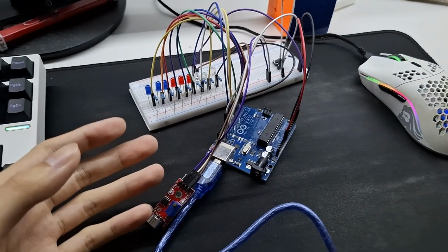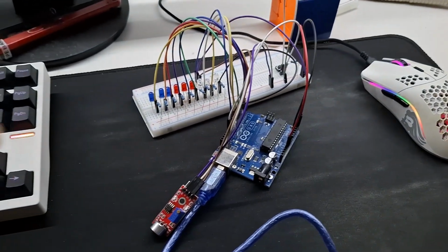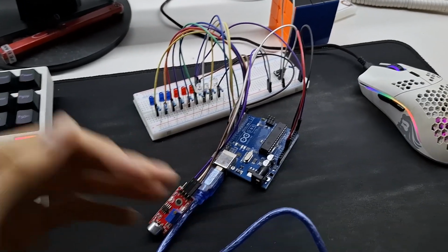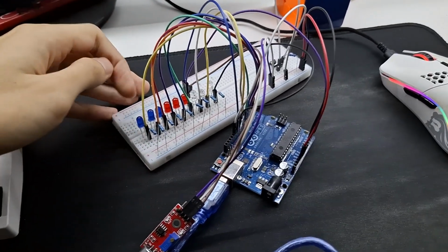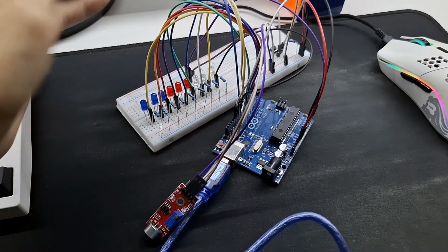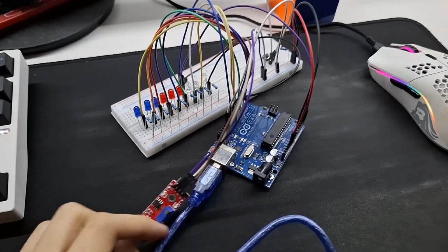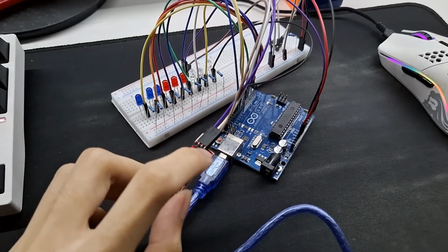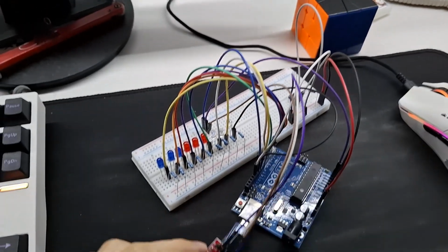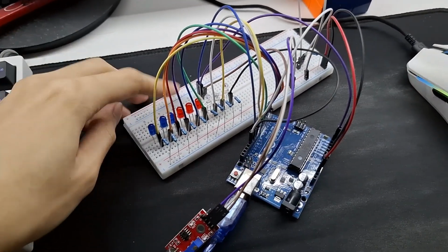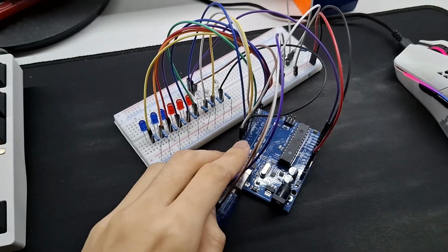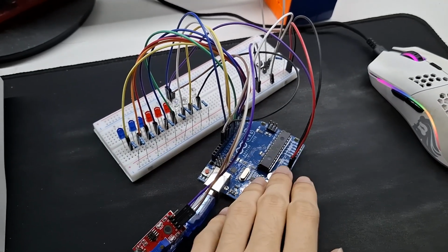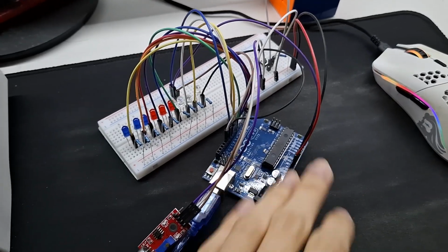to the other mode, which is frequency detection mode. It will detect the sound frequency that hits it and will display it on the same LEDs. All of this is done by splitting the analog output of the sound sensor to wire to both the digital input and analog input of the Arduino board.